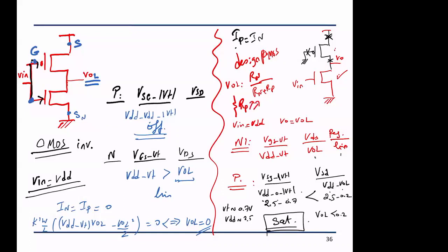So it will pull things up slowly. So anytime a pull-down path competes with it, it will pull things much faster. It will have low resistance and connect me to ground. We refer to this like it's a keeper device to keep the high level. It doesn't need to be strong and have low resistance, so it is a small device. It has a small W over L, meaning it has large resistance. Okay, thank you, Mario.